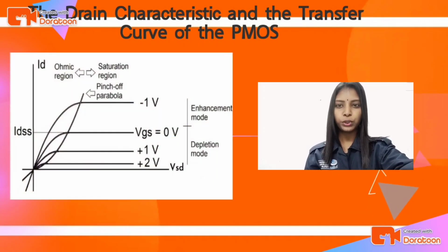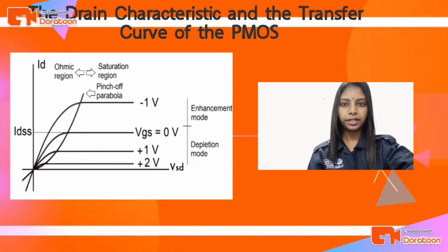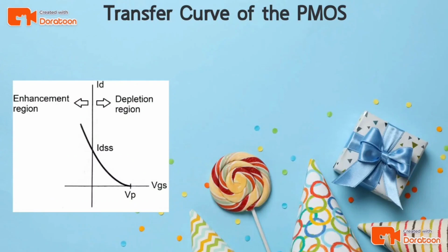The figure beside me shows the drain characteristic for the P-channel depletion MOSFET. VDS has negative values, ID positive values, and VGS has the polarities exhibited for the new reference in voltage polarities and current directions. The drain current increases from cutoff in the positive VGS region, depletion mode, through IDSS. The figure shows the transfer curve for a PMOS. The polarity inversion in VGS ends in a mirror image of the transfer characteristics.